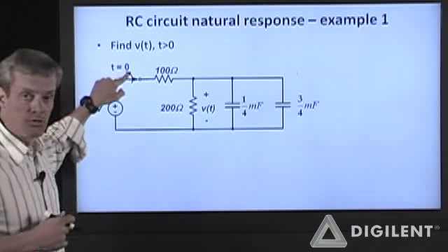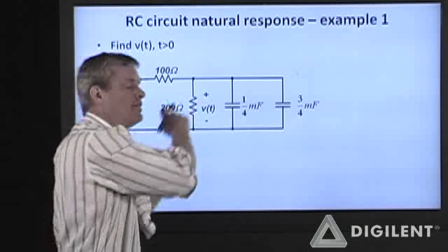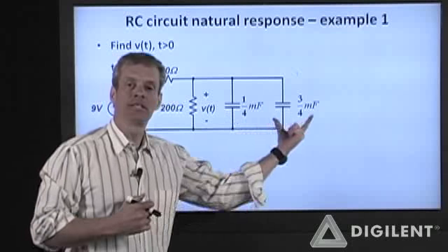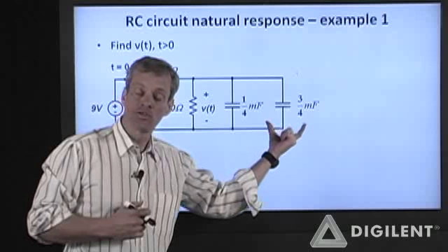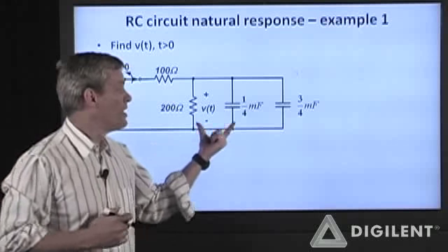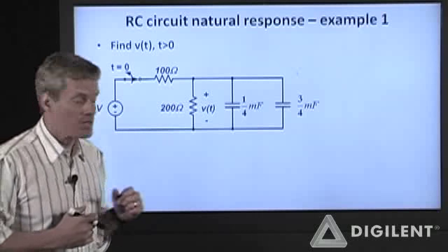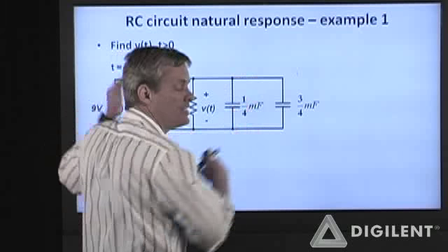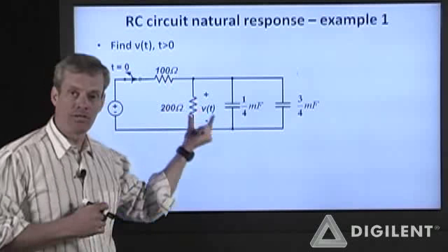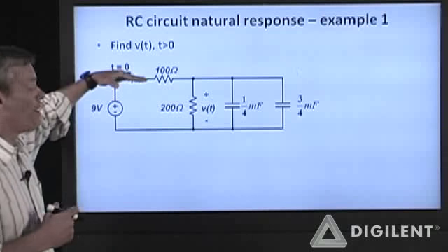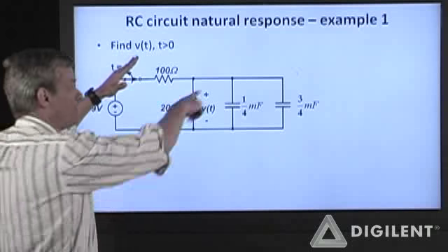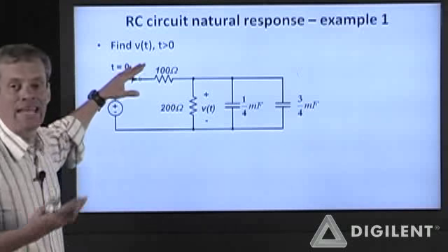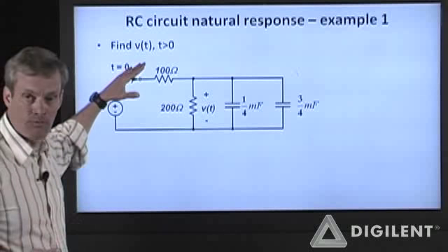So before t equals 0, I'm actually applying energy to this circuit that will result in some energy being stored in these capacitors before I open this switch. Now, after I open this switch, this initial energy in these capacitors will dissipate through these resistors. So after I open this switch, the circuit over here will be doing a natural response. It will no longer be forced.